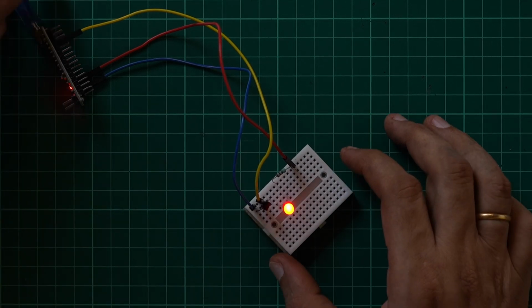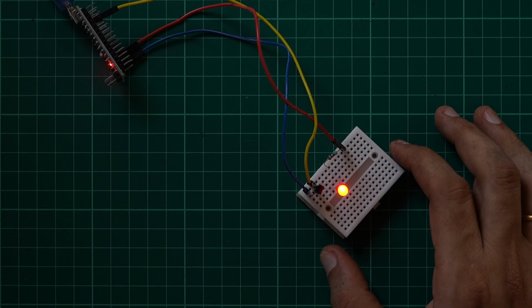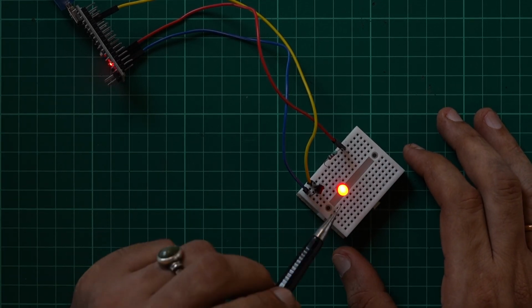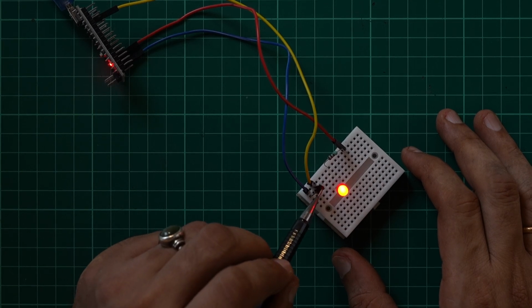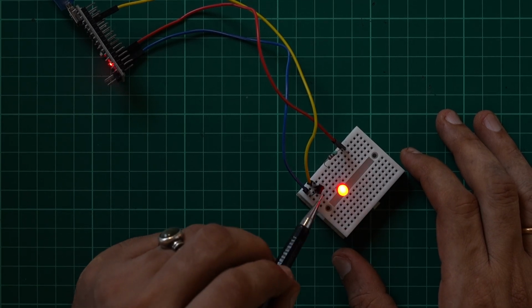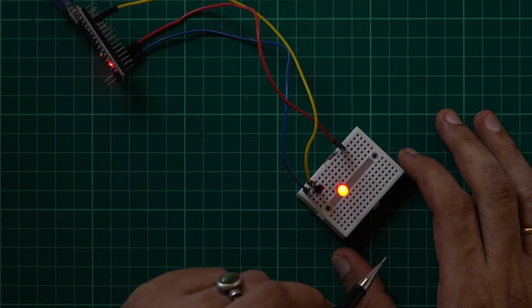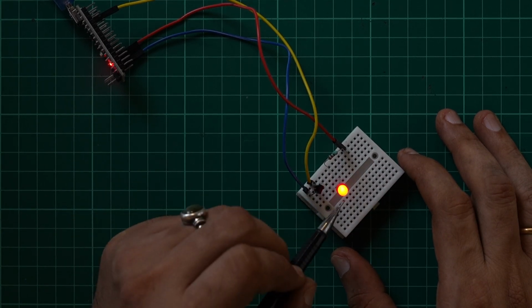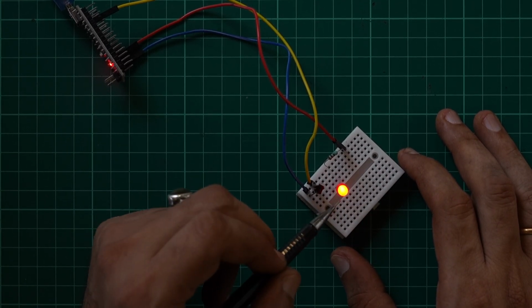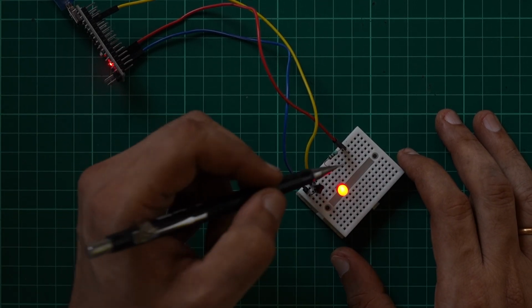So I have wired up a simple circuit here. It's basically an Arduino Nano, and there is an LED which is connected to a transistor, and we are going to look a little bit more into why we are using the transistor. There is also a resistor to make sure that the current through my LED is limited, because the LED works at roughly around 3 volts. The supply that I have connected from the Nano is at 5 volts, so we need a little bit of current limiting in this.